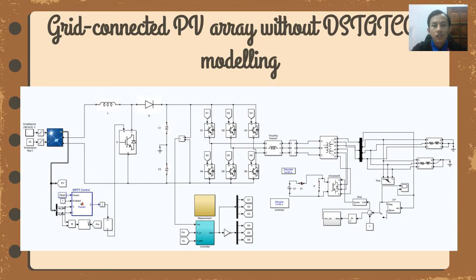It consists of an arrangement of several components, including solar panels to absorb and convert sunlight into electricity, a solar inverter to change the electrical current from DC to AC, as well as mounting, cabling, and other electrical accessories to set up a working system. A detail of the PV array model is a 100 kilowatt array connected to a 200 kilovolt grid via a DC-DC boost converter and three-phase three-level voltage source converter (VSC).